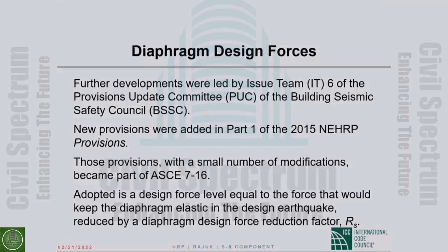Okay. Does that require collector elements? I do not see that. I think the column shear will go through the slab without your inserting collectors, and why you cannot have connection with the grade beams, that again is not clear to me.